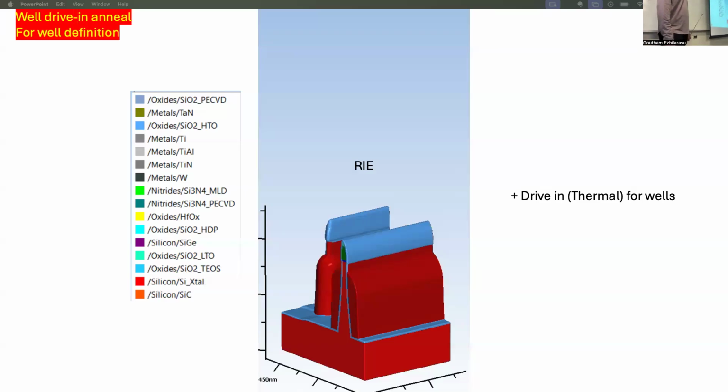That's to control, because if you put poly, first of all, you don't want to put polysilicon directly on silicon because it tends to contaminate the silicon, since it has grain boundaries and all. So you always put a thin barrier layer. All it does is control the amount of diffusion you have. That's oxide. It cannot be a nitride, but it can be a thin oxide.